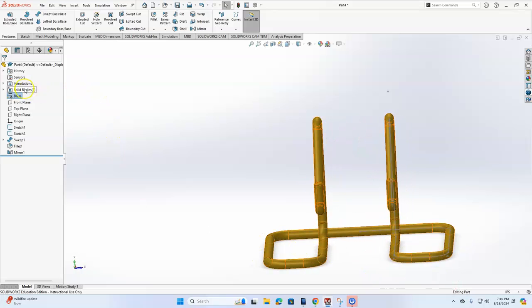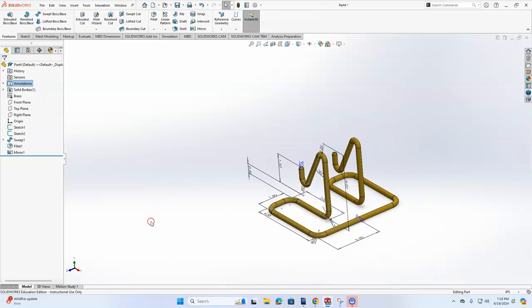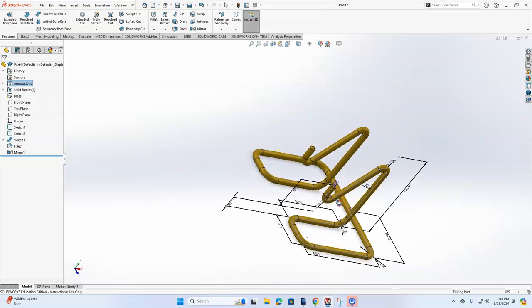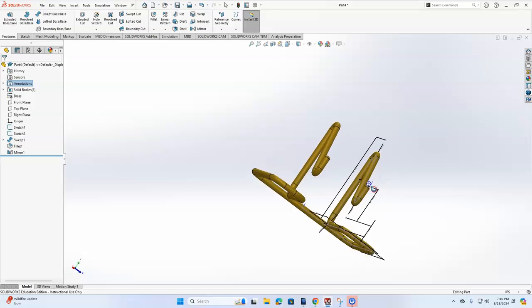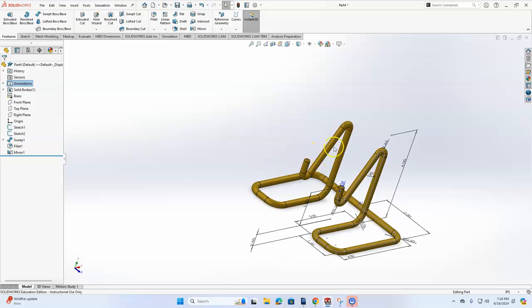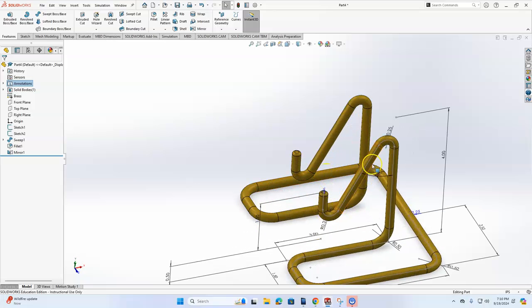Well, let's see finally the feature dimensions. It will show me all of the feature dimensions from the sketch, like for any other features that we work with. So in summary, the sweep features are great when we can define something as a cross-section traveling over a path. In that case, we should always use the sweep. Alternatively, how would we make this object?